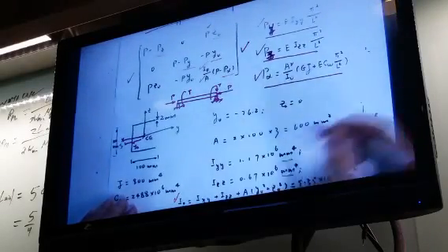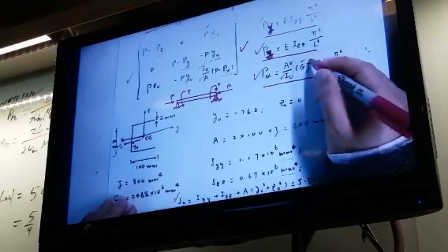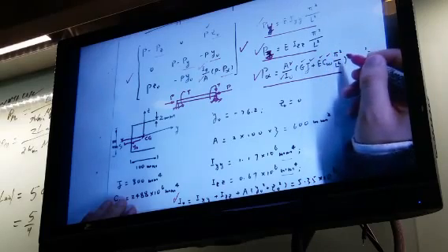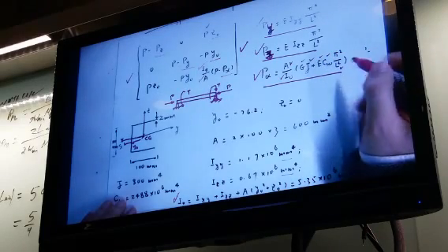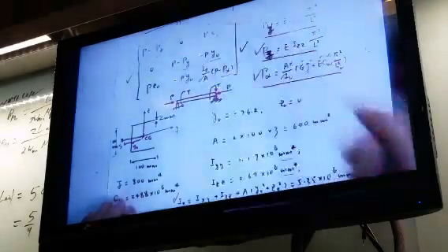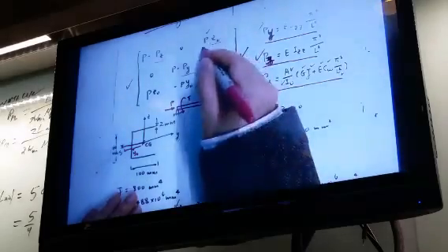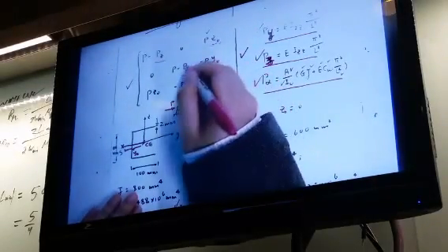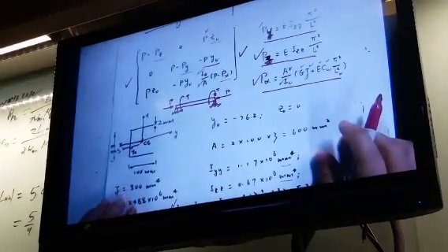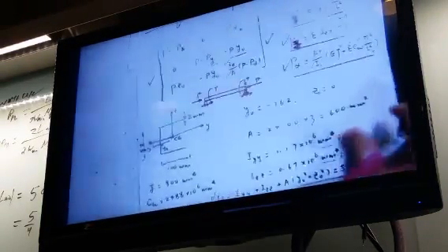So when you have that prepared, you have A, you have I0, G is shear modulus, J is torsion rigidity, E is Young's modulus, there's a warping coefficient, L is the length of the beam, and you have everything, and then you can put all of this number into this matrix. So this is Pz0, this is Py0, this is Py, this is a sub-index of Py. You have a 3 by 3 matrix, and to make the determinant to be 0,